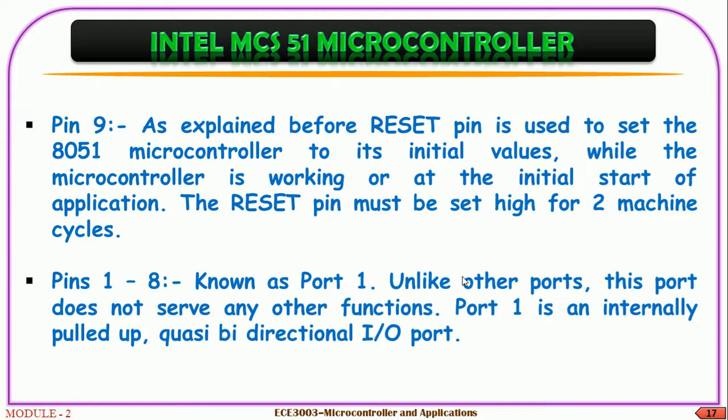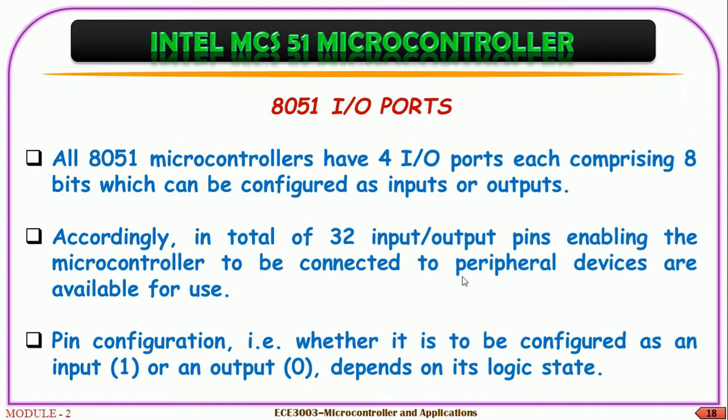Unlike other ports, this port does not serve any other functions. Port 1 is an internally pulled up quasi bidirectional IO port. Then 8051 IO ports. It has 4 IO ports, each comprising 8 bits, which can be configured either as inputs or outputs.